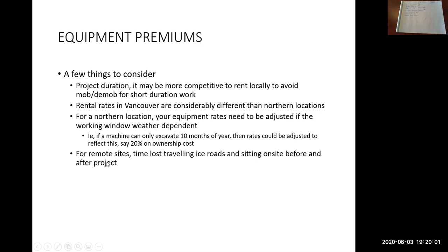Thinking about cold climates, if it freezes overnight and then things thaw during the day, that off-road access may turn into such a mucky quagmire that you cannot get a low bed in during the day. You may have to bring the truck in at night when things are frozen.